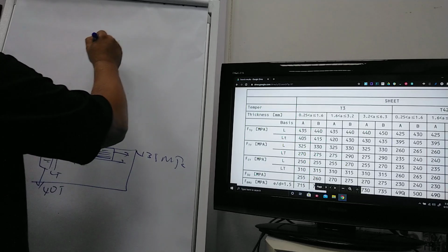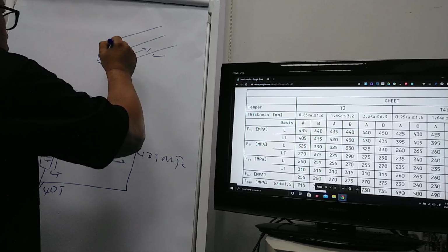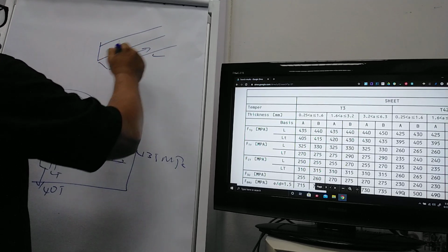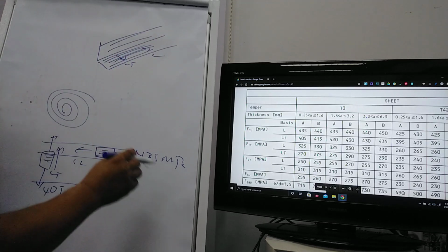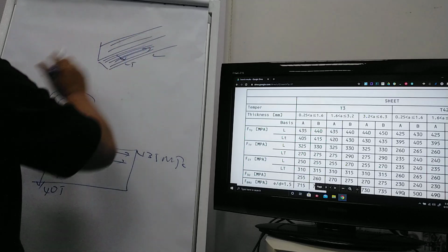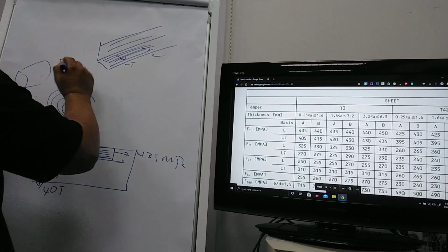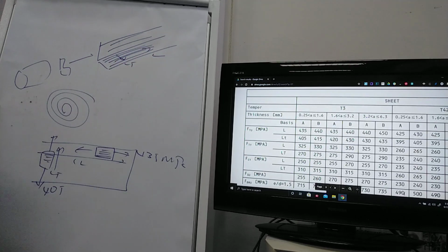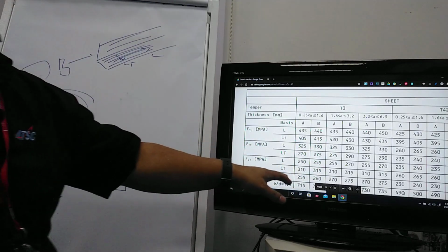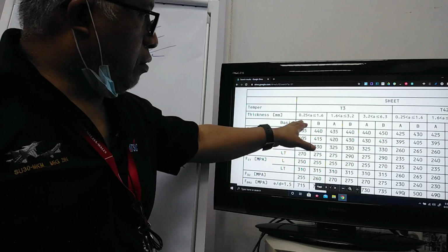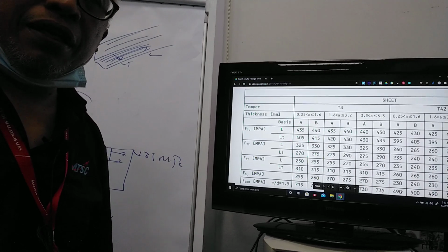Similarly, if you have an extruded angle, this is the L direction. So this is the LT direction. L direction, I can say, is parallel to the grain, and LT is transverse to the grain. So when they draw this to get L, there's a billet here. They draw it through the die, the die pushes through, and then it comes out with this angle shape. So that is how we need to determine engineering allowable values, and you have to know what A, B, L and LT are. So that is how we identify those values.